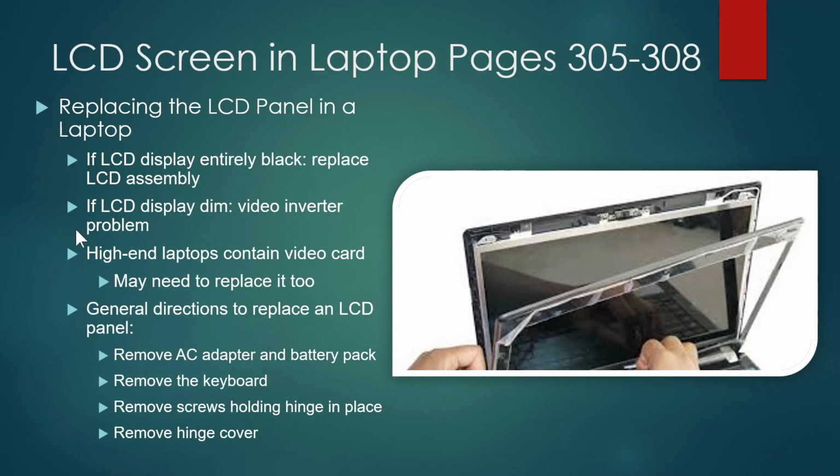And once again, if the laptop's so old that it has an inverter, you're probably looking at replacing the laptop rather than spending money on this old laptop. You can get the screen probably for $80 or $100, and you can gamble. If it's that old of a laptop, you can gamble and only buy the inverter, replace the inverter, and then if it still doesn't work, then you know you've wasted $30. But now you've got to go get the screen with an inverter or a screen without the inverter and use the one you bought.